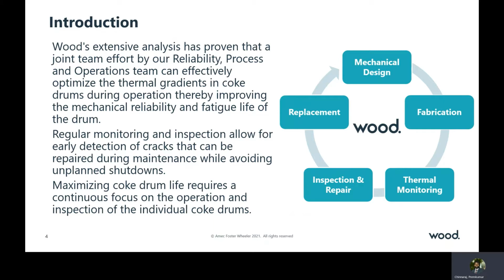We also provide enough inspection windows and lanes in our design to inspect critical areas of the drum for early detection of cracks that can be repaired on time to avoid unplanned shutdowns. Therefore, a combined effort is necessary between reliability, process, and operation during the entire life of the drum. At the end of the life cycle, we also assist our clients in coke drum replacement studies.